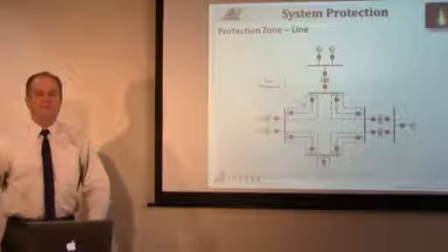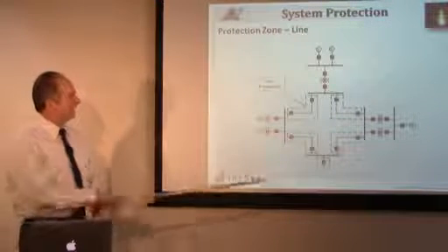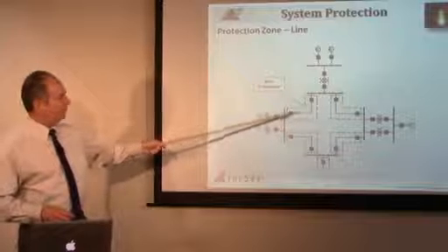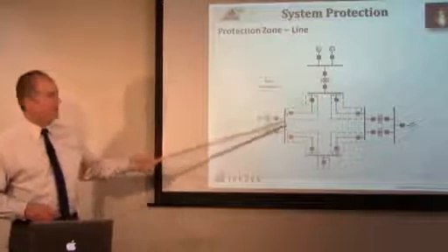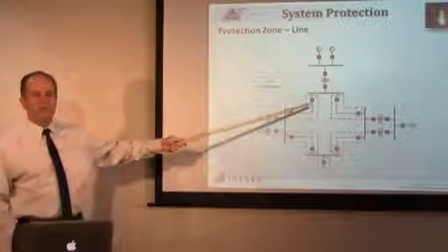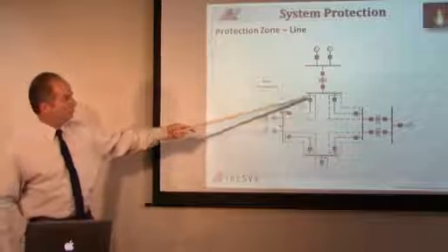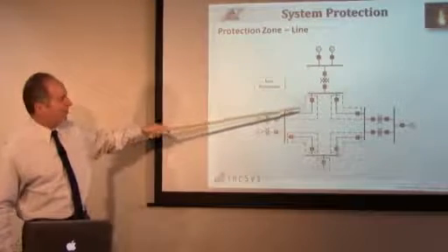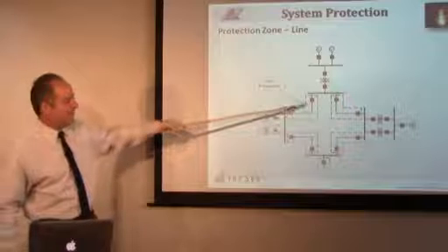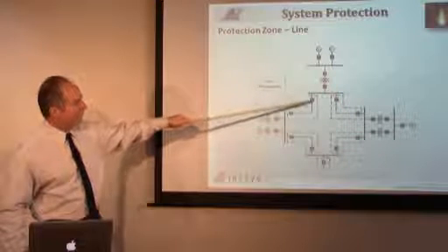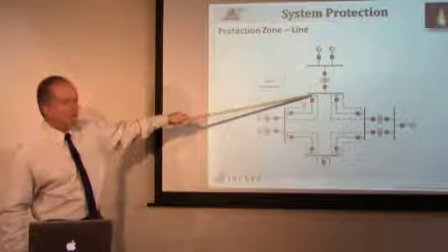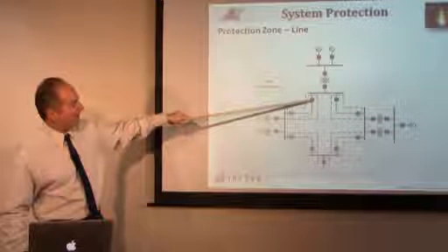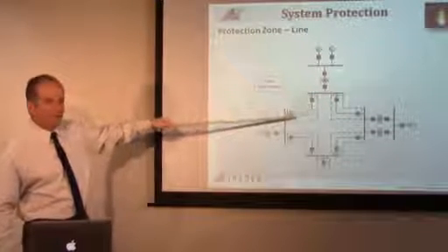Now let's talk about line protection. On a transmission line, we're protecting this particular line using these two circuit breakers. Now, when we're setting up protective relay schemes, we're using the CTs on the opposite sides of the breaker. That provides overlap. For example, we're looking at CTs on the bus side of that breaker for protecting that line.